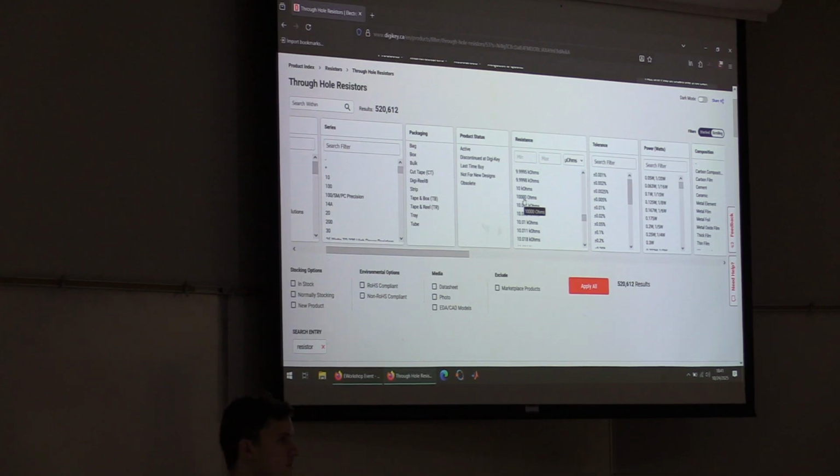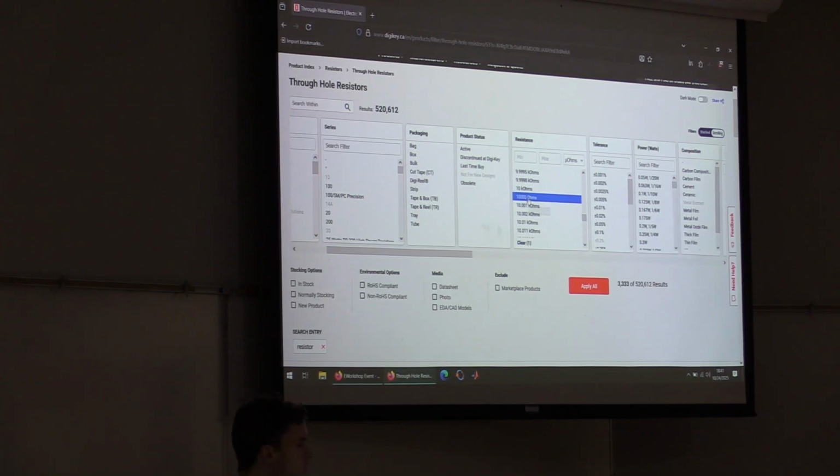Typically, component values for passive components, such as resistors, capacitors, and inductors, will follow what's called a standard value series, which is based off of the tolerance and all that. The most commonly used is the E series of preferred numbers. Wikipedia has a great page on that. And then I believe the schematic best practices document also has a little excerpt on that.